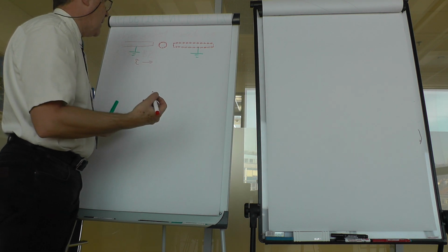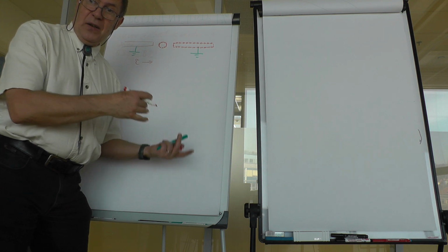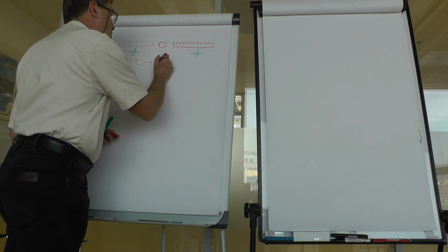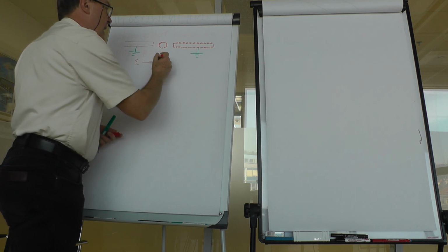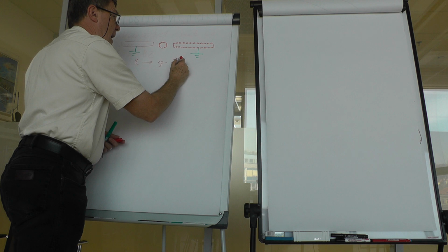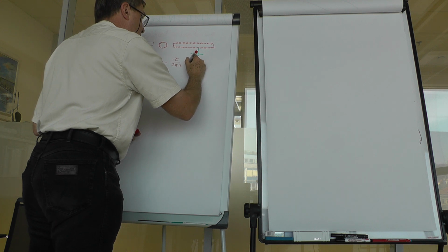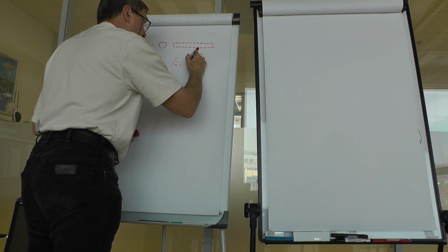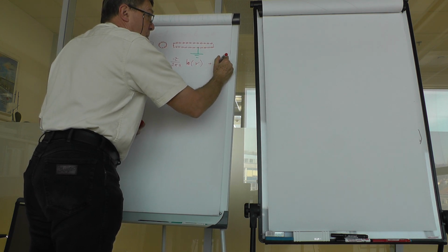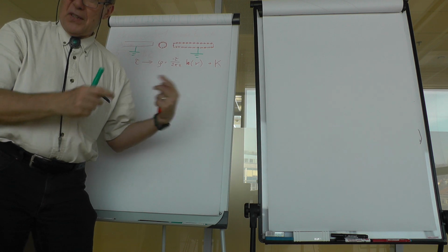an electromagnetic field that could be expressed in terms of flux density or electric field strength or potential. And the potential around such a conductor is given by minus tau over 2 pi epsilon, where epsilon is the permittivity, times the logarithm of r plus a constant, of course, because a potential should have a constant, where r is the distance from the center of that wire.